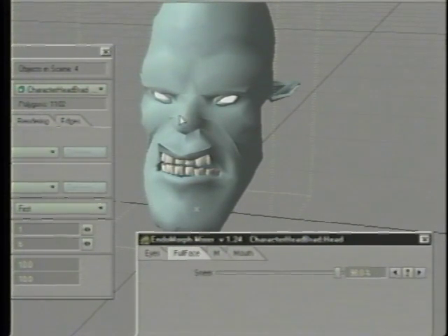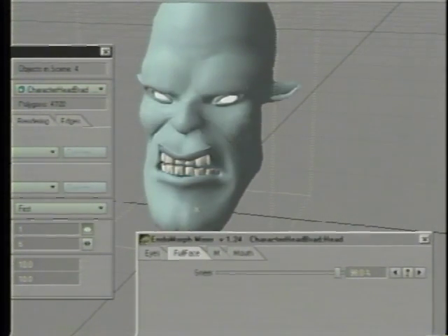And again, it looks a little rough here, but keep in mind the end result is going to be much more smooth, and we can change and see that by updating our subpatch display level to match more closely the subpatch render level. So again, you can have something like a 10. You can see now it's very smooth. Or down to a 2, which gives us a nice compromise between speed and nice looking.